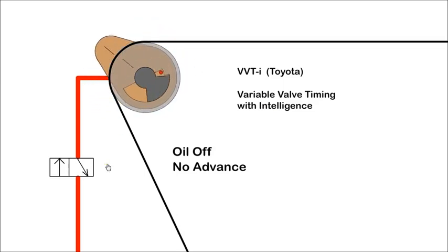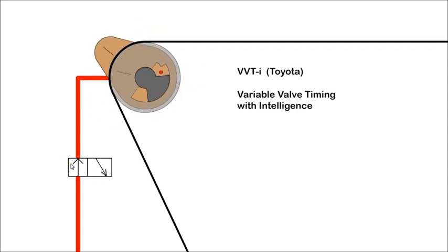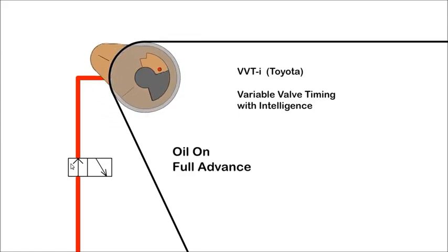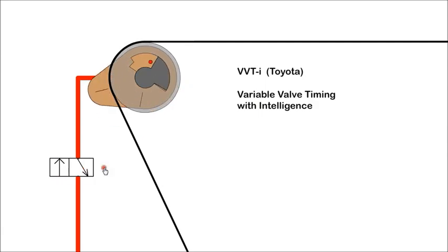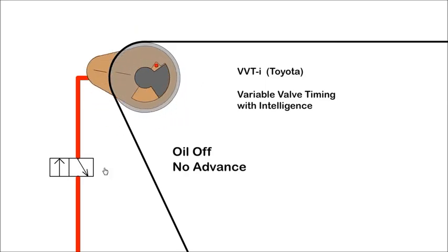It is normal to adjust timing on the inlet valves. With a double overhead cam engine, it is possible to adjust both inlet and exhaust valves independently of each other. Note, VVT only adjusts timing, but VTEC adjusts both timing and lift.